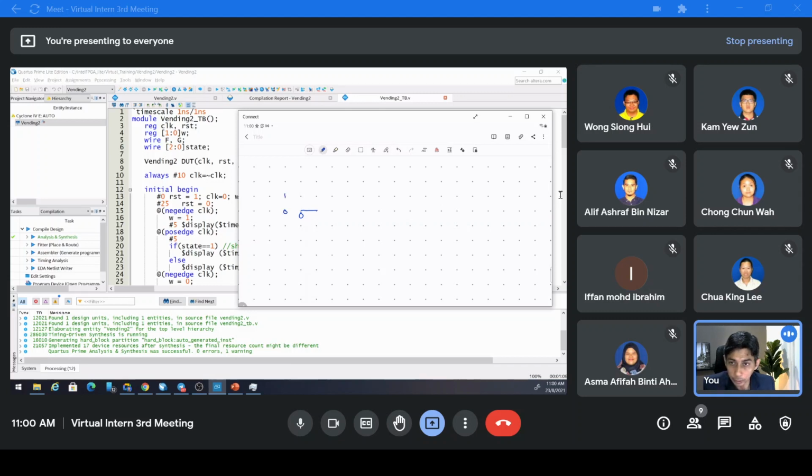This is logic 1, for example, logic 0. And it will be 0 for 10 nanosecond, and will go to 1 here, and it will be 1 for another 10 nanosecond, go back again to 0, another 10 nanosecond, and go again. All right, it means that the period is 20 nanosecond.